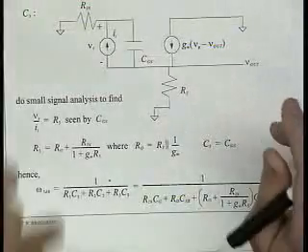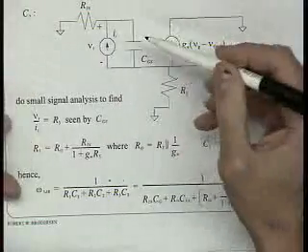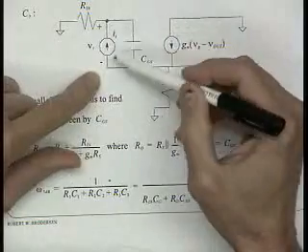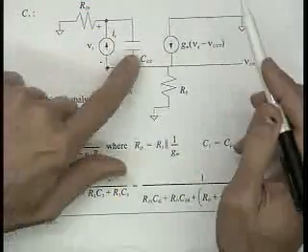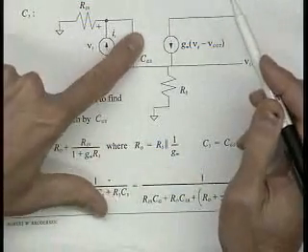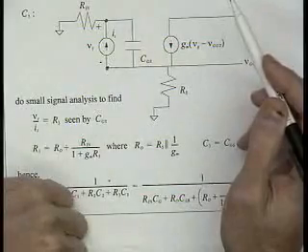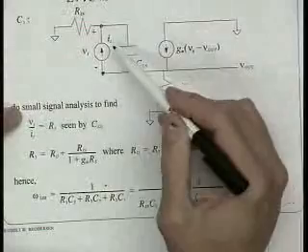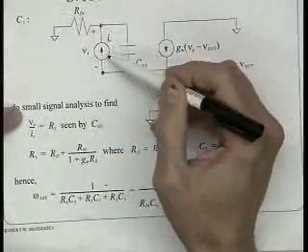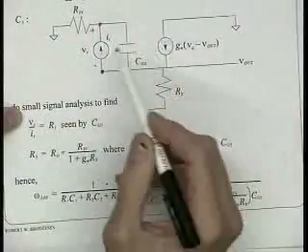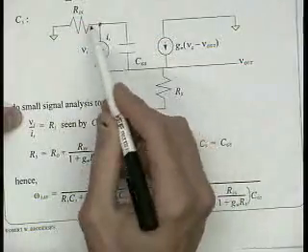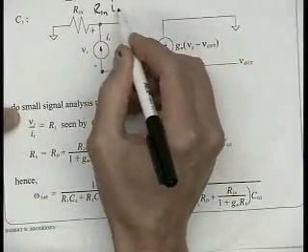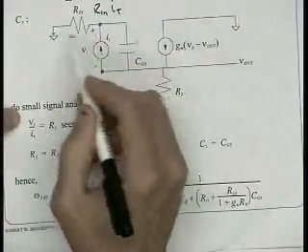This third one's even nastier. What we do is put a test voltage across where, it's CGS now. Put the test voltage across that and calculate what IT is. What's IT going to be? I'm forcing an IT, so we can figure out what the voltage on this side is. It's going to be Rin times IT. That's the voltage drop across this side.